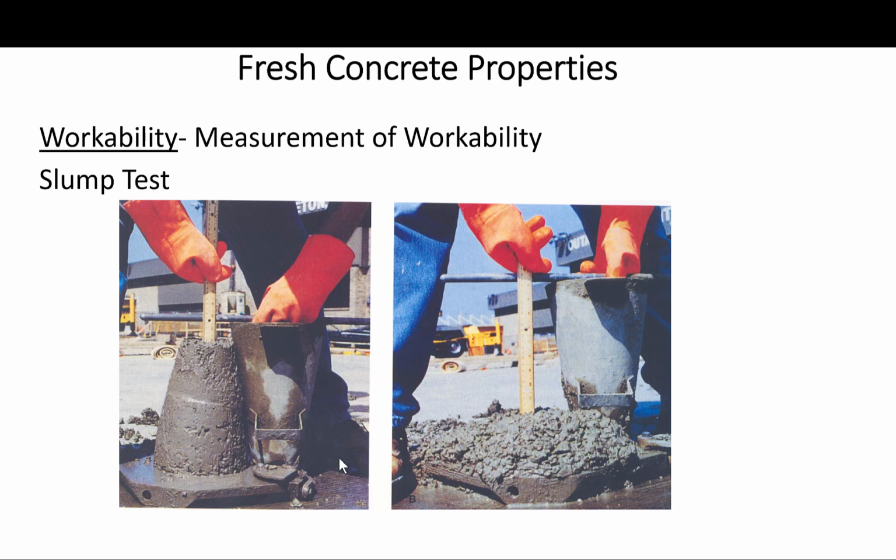It also has to be noted that none of the available test methods can be used over the whole range, very wet to very dry concretes. So an individual test method can only be used over a relatively low range of workabilities. You cannot use these different test methods interchangeably. As I will show in an upcoming slide, they're used for different types of mixes.